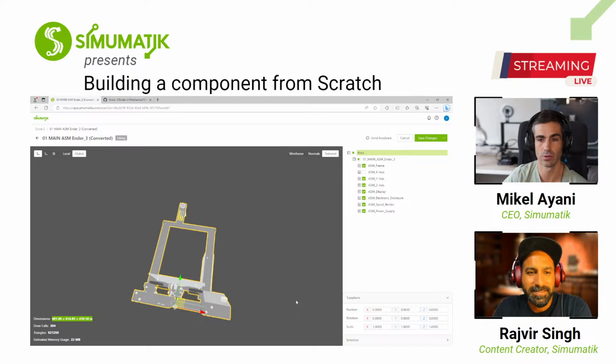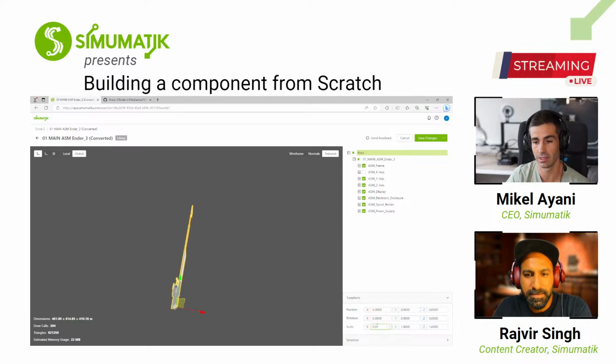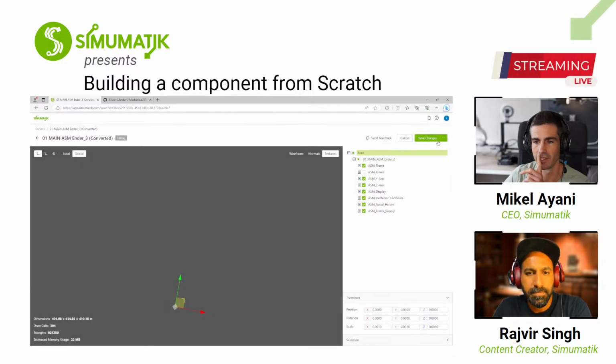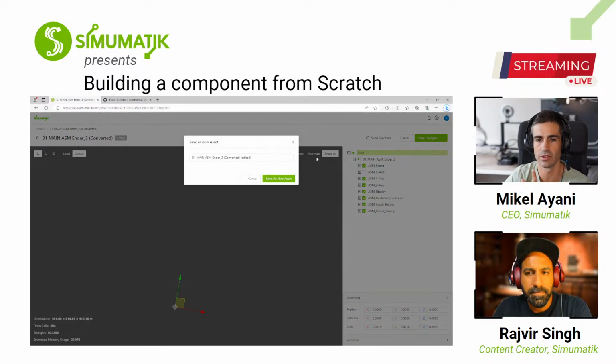We are going to do two things. We are going to fix the scale, and we type here 0.01. Okay. And if we fix this everywhere, now we can save this. We are overwriting the 3D model. Sorry, we are going to overwrite it with another name. We are going to call it the Ender 3 base.